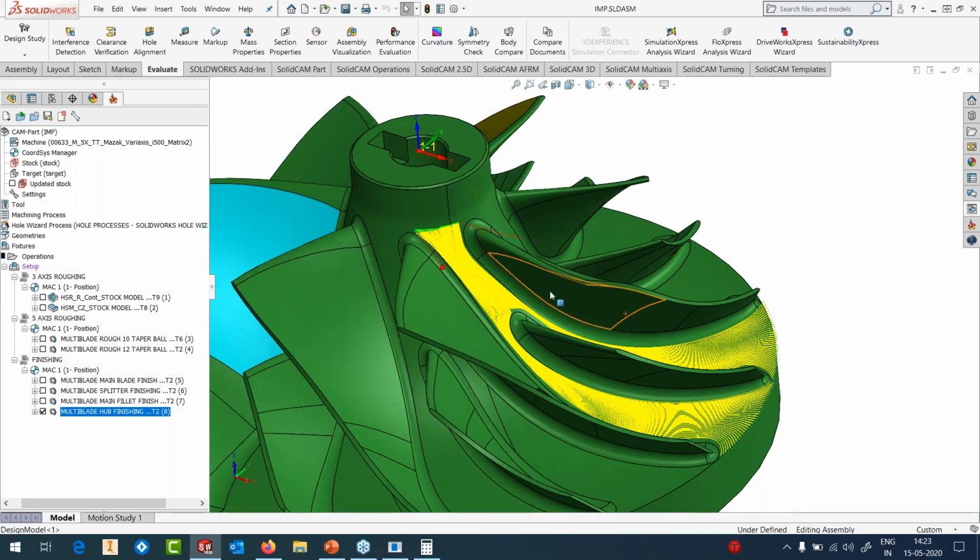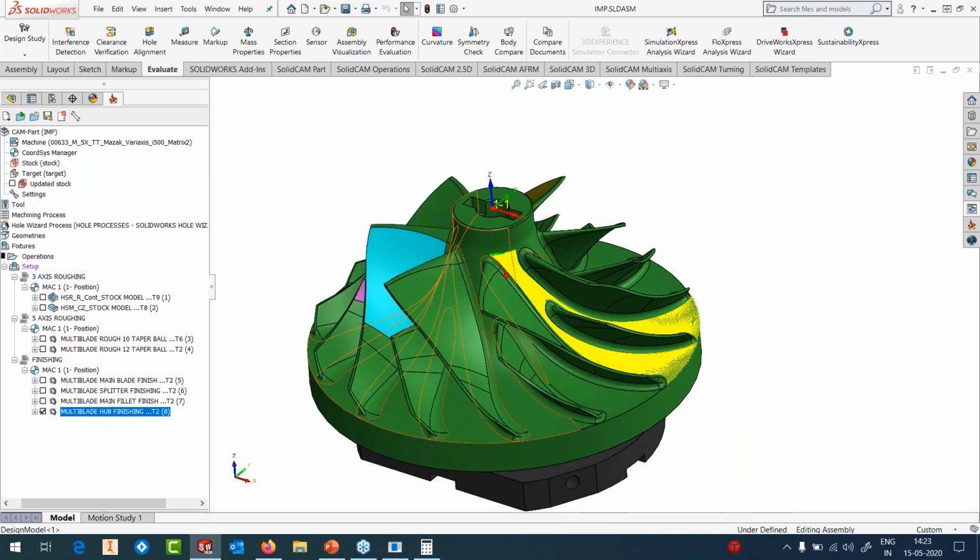How much stock to be kept for finishing? Well, it depends on the geometry. This particular part, we used to do it at the exhibition at IMTEX last year, and we almost did 1 impeller per day on all 7 days. So we had kept a stock of about 0.7 for finishing, and that was good enough for us to finish this.